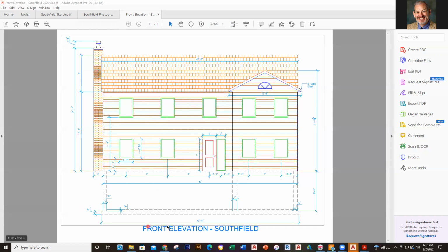Notice at the bottom, you have this. The bottom is the basement. The basement is what is under the ground. Therefore, that's why it is being indicated here by dashed lines. When you have dashed lines, that indicates it's something that's not visible in the view you're at right now. And that wouldn't be visible, because it would be underground. So that's how that works, and that's why that's done.